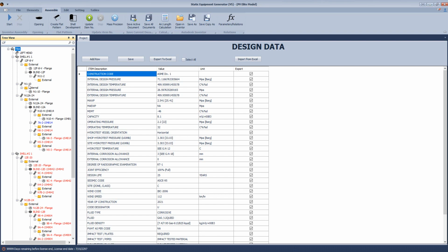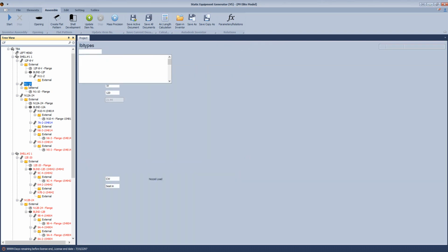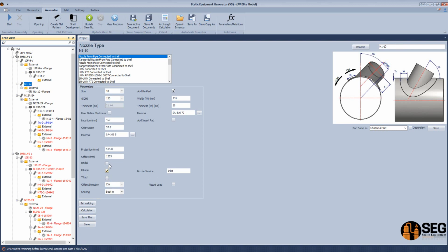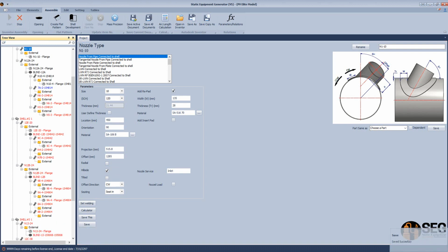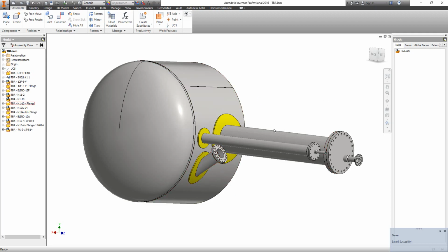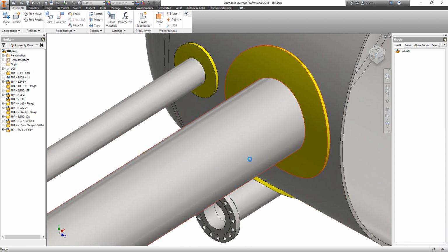So we can make a modification for this nozzle by hand by making it a helical side nozzle and modify this orientation to make it 90 degrees, clockwise or counterclockwise. So let's modify this value and click on start to modify the orientation of this nozzle to make it a helical side nozzle with 90 degrees. Now let's complete the other nozzles creation.